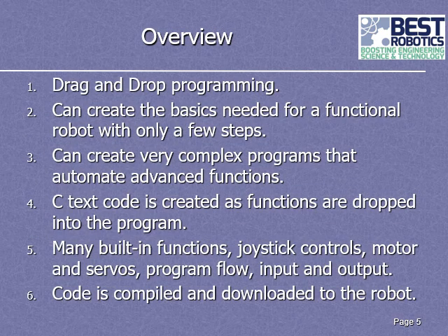EasyC is basically a visual programming environment where you drag functions from the function list and drop them into your work area. You don't have to write low-level lines of code. You'll drag a function from your list of functions, drop it into a work area. You'll get a pop-up, and it will request you to enter some specific data to make that function do exactly what you want it to do.